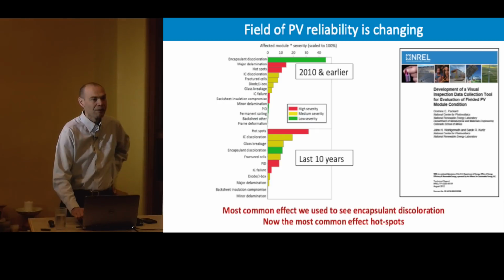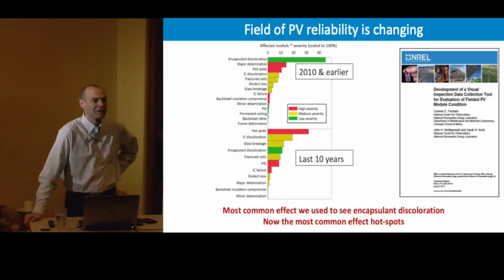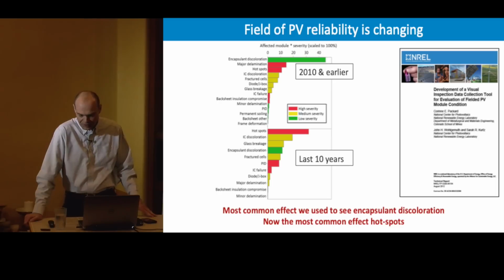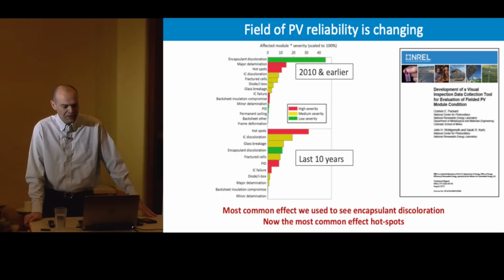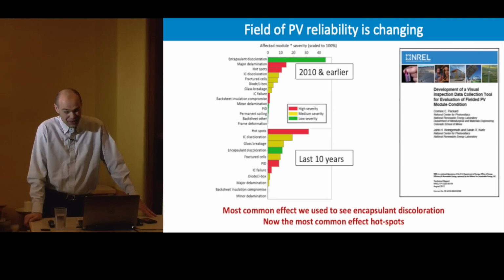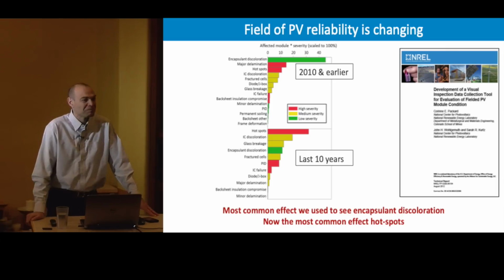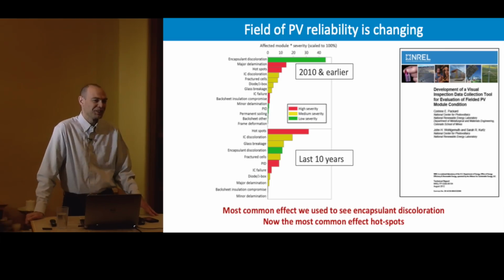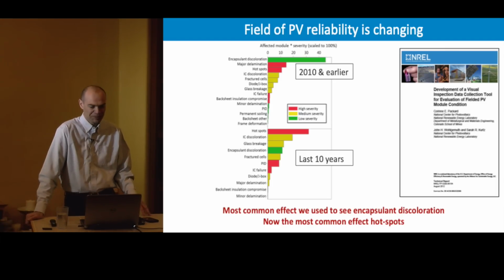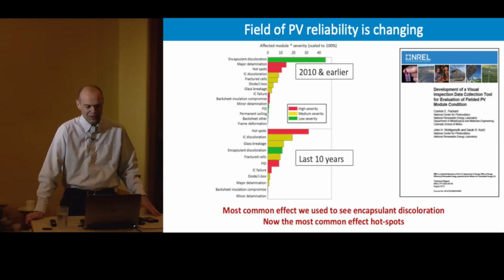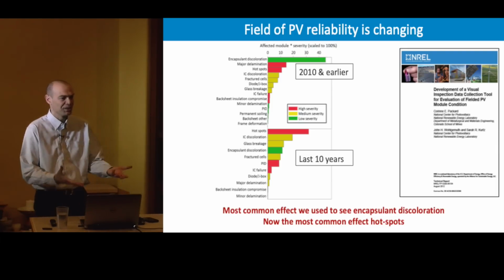Maybe you're going to talk about this, but would that apply to hail, where the hail may not break the glass? Great question. Damage the cell? Yes. Okay. So that can happen with hail. You probably all remember May 2017. We had 1¼ inch hail at NREL. Some modules were broken where the front glass was shattered. No, I don't think I have a picture of that later. But the front glass can shatter, and it's very obvious.